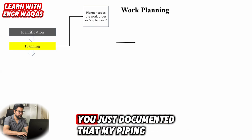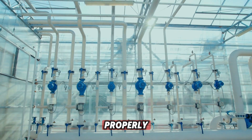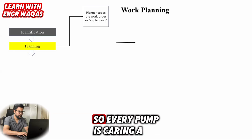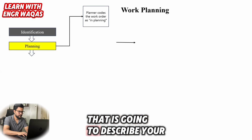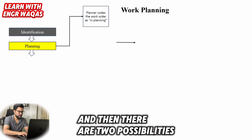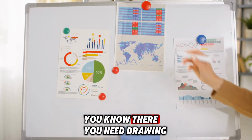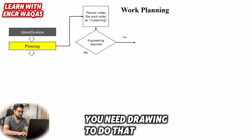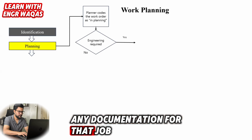From identification, you have just documented that your piping is not working properly, your instrumentation is not working properly, your pump is not working properly. Maybe your plant is carrying 200 pumps, so every pump carries a certain code. You have to document that code, which is going to describe your future shutdown management task. And then there are two possibilities. One is that you need drawing, engineering, meaning you need a drawing to do that work, or you don't need any drawing or documentation for that job.